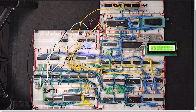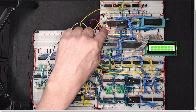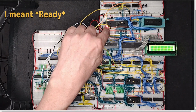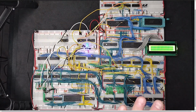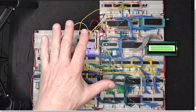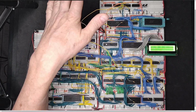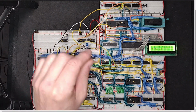And because of that, if we were to just be in the wait, so if I press this and now the computer is in the wait condition, I have this set so that when reset is low, the light is on. So the reset is low now, so the LED is on. It's waiting for a negative on the interrupt. And if my interrupt system was providing interrupts to it right then, during this time, it wouldn't be able to wait. But now it waits until I push the button because I can disable the interrupts while it's waiting.